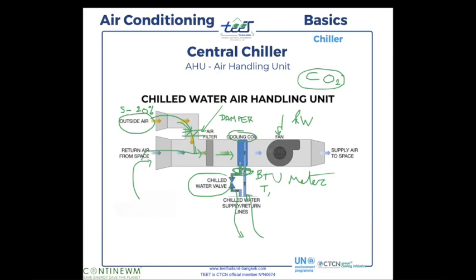So you plug it in. The BTU meter has to measure the temperature of this water line and also the temperature of the return, the chiller return water. So by the delta T and by Fourier's law that I showed before, the BTU meter, and with the flow also, we have a flow meter. What is the quantity per minute or per hour of water that is processed? That will be regulated by the chiller valve.